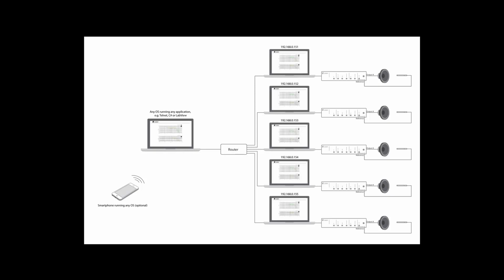TCP/IP also features a more powerful and expandable command format for interacting with SoundCheck. This is extremely valuable to anyone who needs to control SoundCheck from an external program, for example, as part of an overall test plan or factory automation. One computer can control multiple SoundCheck systems, simplifying production line measurements.